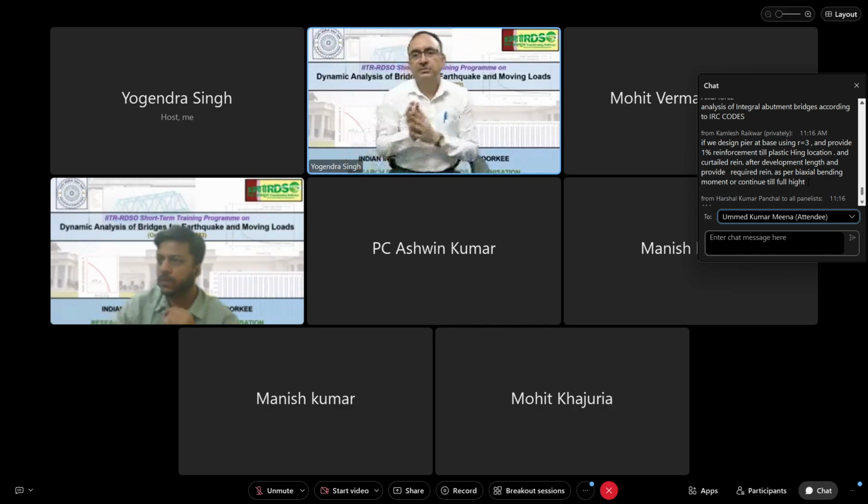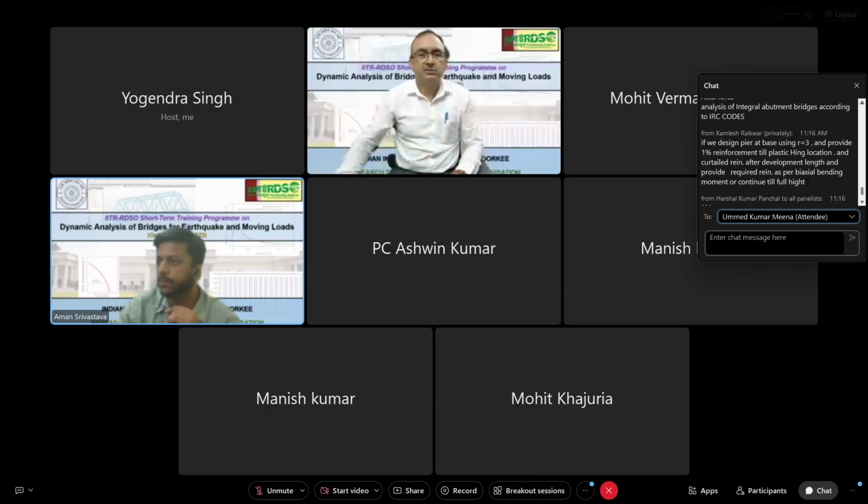Okay, sir. The question is from Kamlesh. If we design the pier at the base using R equal to 3 and provide 1% reinforcement till the plastic hinge location, and curtail the reinforcement after development length and provide the required reinforcement as per biaxial bending moment, or should we continue it to the full height?